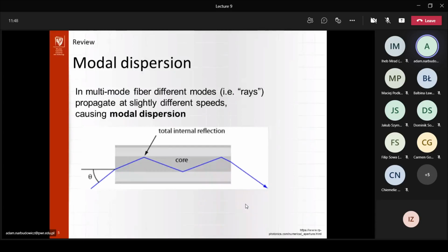So basically, how this can be best imagined is when we talk about the skew rays in optical fiber and meridian rays within optical fiber, right? And you can realize that the meridian waves, which travel just in the meridian or center plane of the optical fiber, will travel a shorter distance than the ray which skews in the optical fiber at an angle.